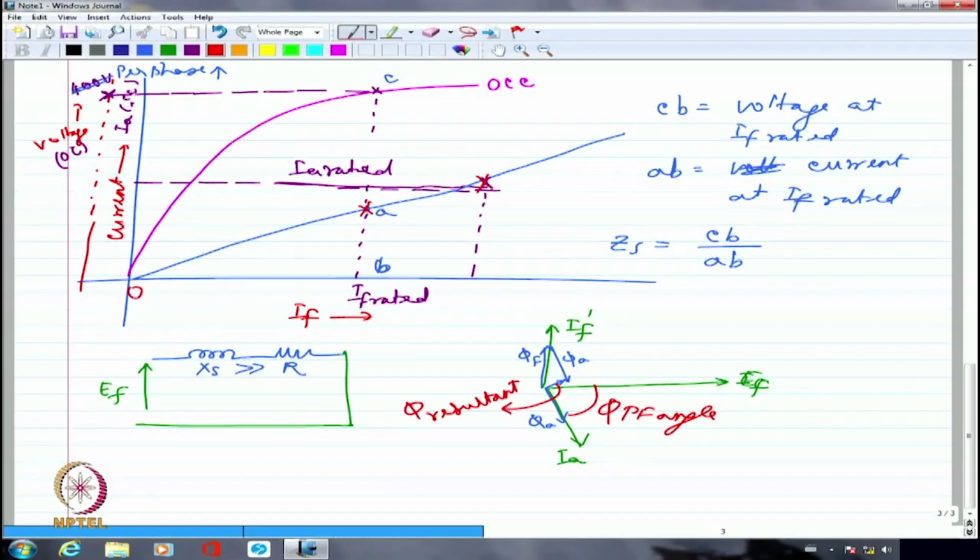whatever, depending upon how much current you have drawn. The same thing holds good in synchronous generator as well. If I am going to have a leading load, I can have the voltage regulation to be negative. If I have a lagging load, the voltage will plummet. It will really go to lower values. If I am connecting it to infinite bus, how can the voltage go to lower values? It cannot, because the infinite bus would say, you better maintain this voltage.